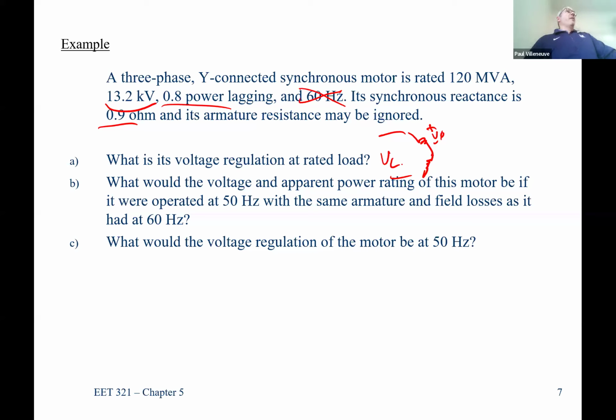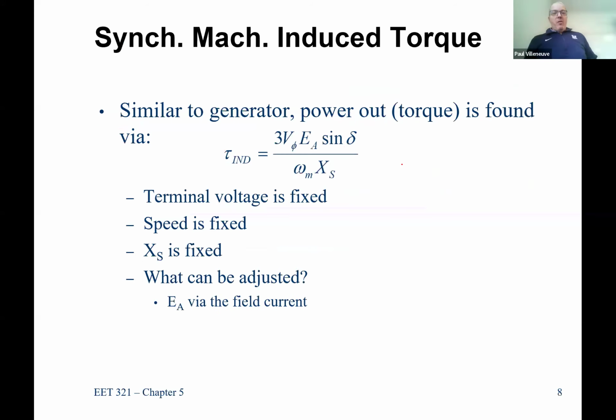And again, it gives you a little more ability, because if you run 208, you have the ability to do 3-phase. Most single-phase loads that need a higher voltage can operate at 208. I'm thinking of an example. Anybody here know what an electric dryer is, right? That's running at nominal 240. But if you connect it at 208, it usually will run perfectly fine. Maybe not have quite as much power output, but it runs perfectly fine. Same thing with an electric stove, right? Running it at 208 volts, not going to cause any problems. Sump pumps, well pumps, probably fine running at 208 volts. Not going to be an issue. All right. So if you've got 3-phase, keep it going there.